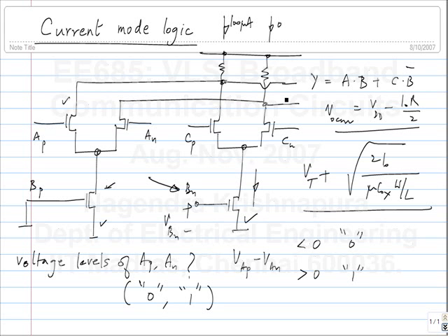What happens now is the current is dependent on the tail source, so the output common mode and the output swing, everything changes. This is not a desirable situation, because when you have a bunch of these circuits, you may not be able to drive the next one properly. What you want is some fixed current controlled by a current source. How do we do that?